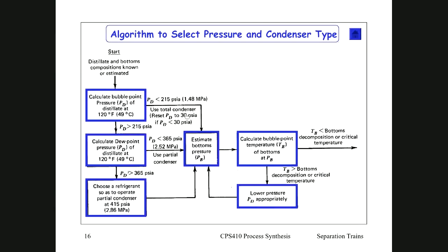That's 2 bar pressure, which seems a little bit more than you really need. But yeah, I just work on 100 kPa atmospheric pressure type of distillation. When you run a distillation column at 100 kPa, you will always try to operate it under a very slight positive gauge pressure.